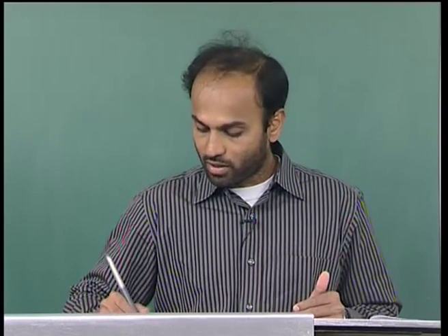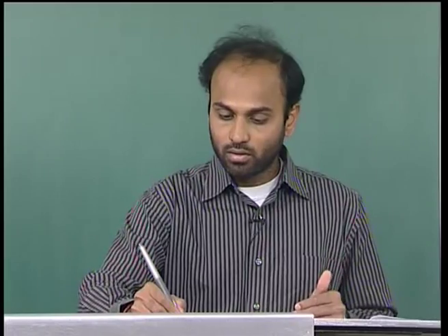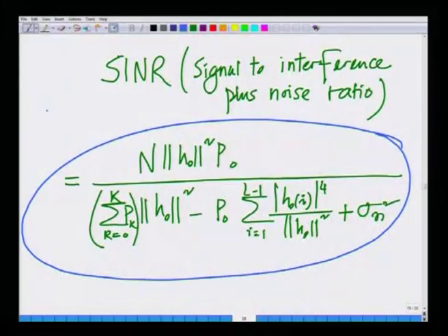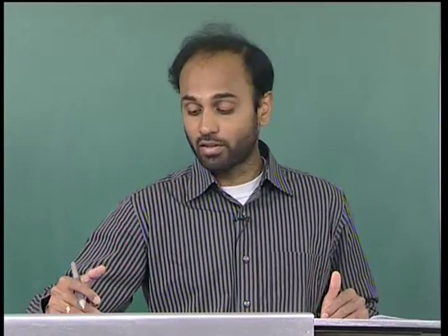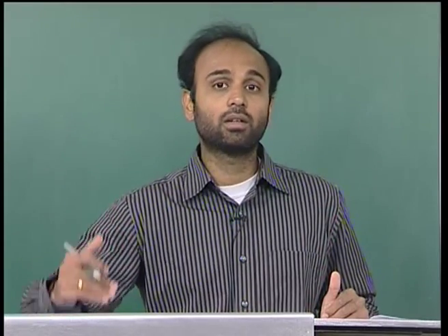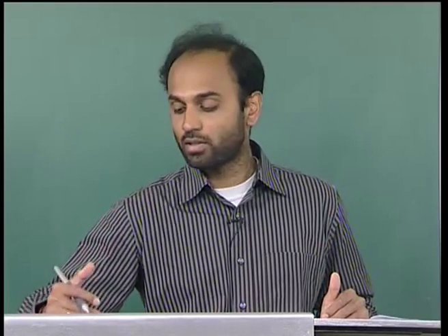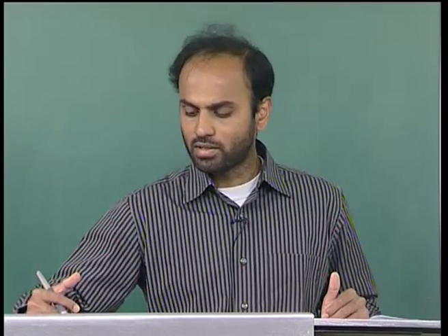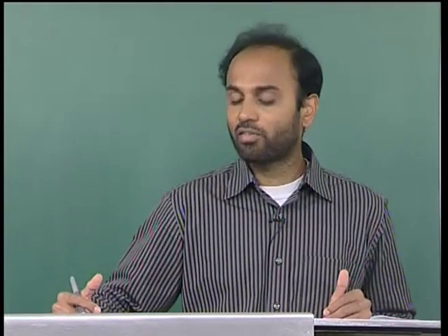what we have arrived at in this expression over here is the actual multi-user SINR of the desired user, taking into account, not neglecting anything. In fact, this is not an approximation, this is an exact expression where we have considered the multipath interference, the multi-user interference and the thermal noise at the receiver. So, this is a thorough expression and it is fairly strenuous, but remember, couple of key observations.